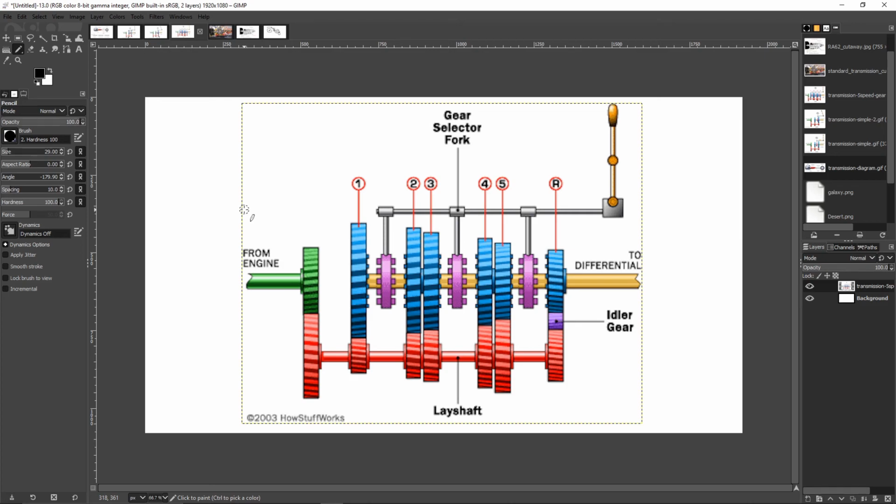Alright, that's fair. So this was all rotating, this was all rotating, this is all rotating. We're moving forward. This output shaft is tied to the rear wheels. I now select reverse, and even if this input shaft is no longer connected to the engine because the clutch is pushed in, these gears are still connected and still moving forward. Then you shift into reverse and it's not going to be happy because it's being driven by the drive wheels.